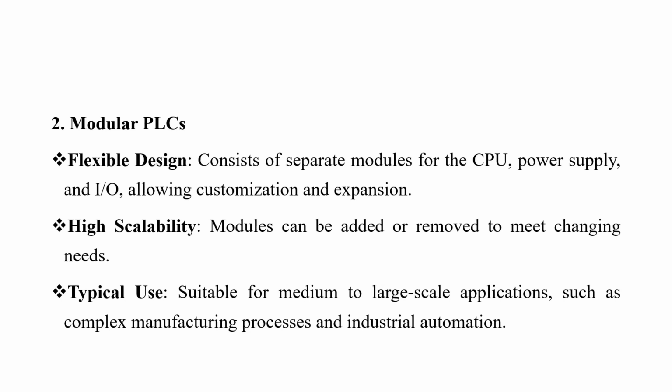Then we have modular PLCs. Those are the modular programmable logic controllers. This one has a flexible design. There is a high level of scalability, and this is because they have separate modules, one for the CPU, the power supply, and the input-output modules, allowing customization and expansion.